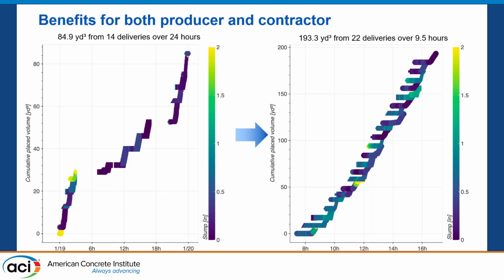Okay, so if you're a lot higher, a lot lower, that shows kind of the variability. This was for a curbing project. And so on your left side, you can see there's maybe an issue with the slump at around 6 hours or before 6 hours, and then it just stops. The curbing equipment started not working. They had to deal with that. You have a break in your production.